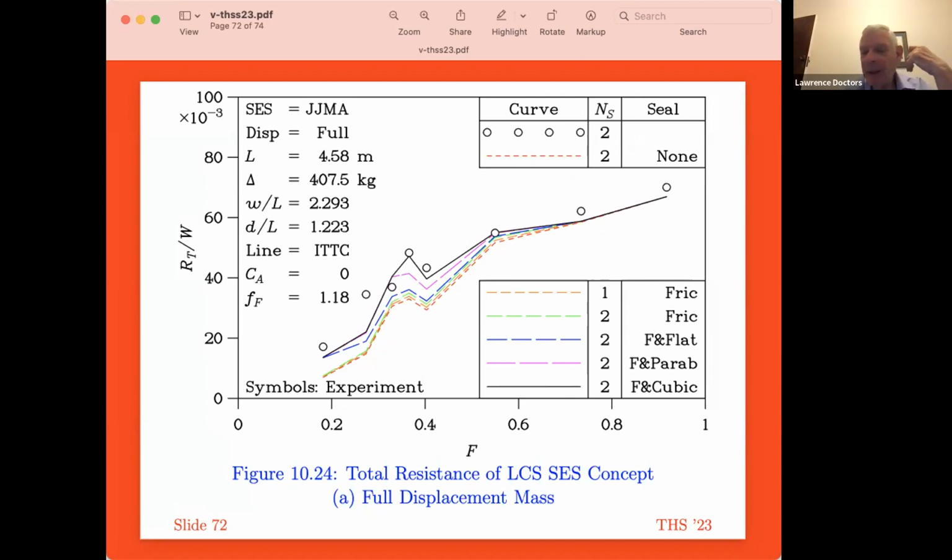But from my point of view, the miracle of the finger is that there are no joints at the bottom to be worn by either the ground or the waves. Yeah, and they reinflate pretty instantaneously, which is quite a nice feature. And of course, if you rip one out, then the adjacent fingers expand to fill the gap up. Yes, it's a fairly damage tolerant seal system.